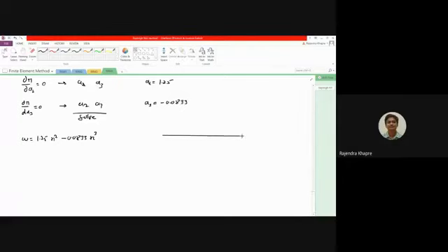Let me draw a straight line over here. This is x equals 0 and this is x equals 5 meters. At this point, if you substitute x equals 0 in this expression, you'll find the deformation is 0 itself. Since there is a fixed end, because of that fixed support there will be zero deformation at this point.